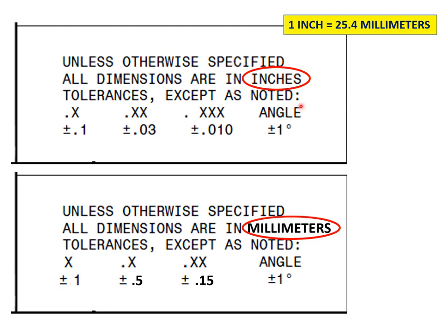In the title block, you always have to call out which unit you are using. So in manufacturing, machine shops, metal forming shops, aerospace, automotive, 99% of the time you're going to be using either inches or millimeters. Here in America for architecture, they tend to use inches. Some old drawings use feet inches with fractions. Now we're going all to decimal places, to decimals.